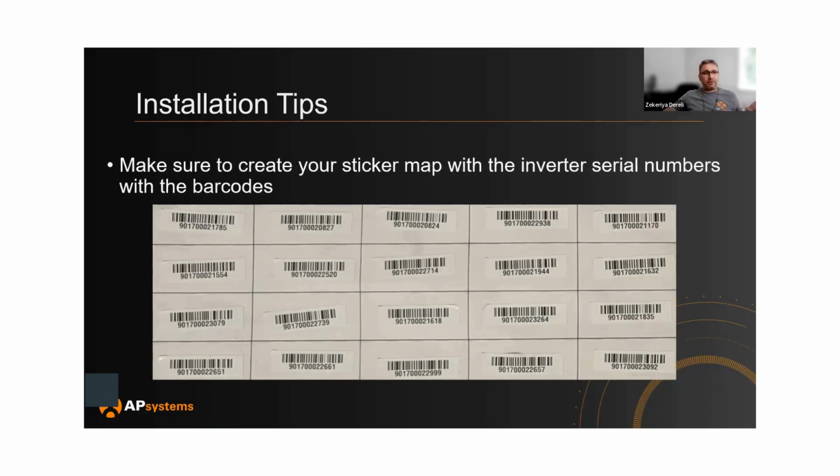And the sticker map is very important when you lay down your inverters. Make sure you peel off the sticker from the inverter and put it on the sticker map. This could be a paper or a cardboard box, but make sure you know where each inverter is located in your layout.